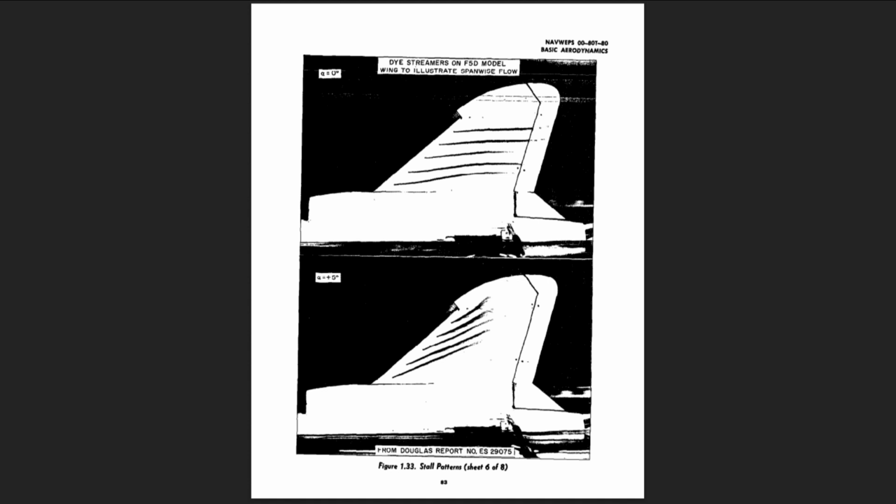F. Sweepback applied to a wing planform alters the lift distribution similar to decreasing taper ratio. Also, a predominating influence of the swept planform is the tendency for a strong cross-flow of the boundary layer at high lift coefficients. Since the outboard sections of the wing trail the inboard sections, the outboard suction pressures tend to draw the boundary layer toward the tip. The result is a thickened low-energy boundary layer at the tips which is easily separated.